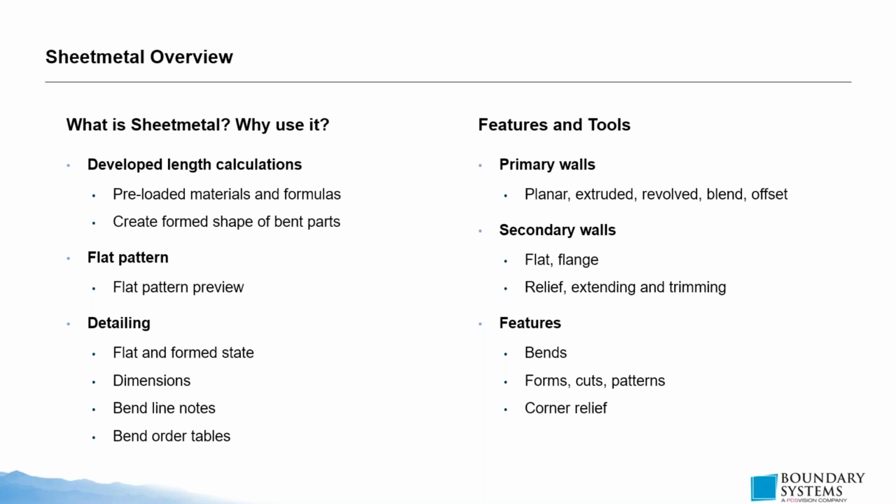In this situation, performing any kind of bend or any kind of feature operation will change the length of the sheet you're working with. So in essence, your initial length and your developed length that you'll end up with after your whole development process is done are going to be different, and that's going to depend on what material you use.